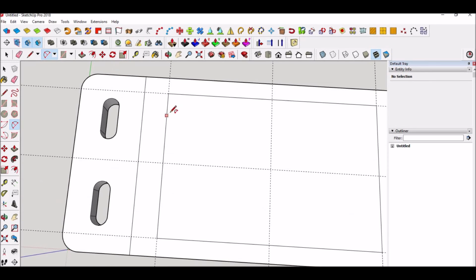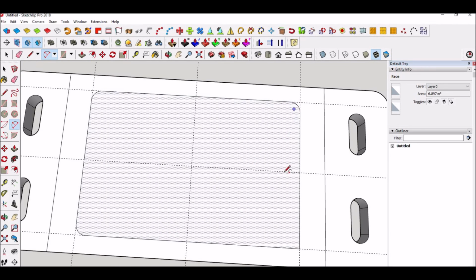So the same thing, click here, tangent, double click, and it did not do it for some reason. There we go. Probably clicked too fast. So 0.15, hit enter, it'll readjust it, hit A for arc, double click the corner, right there, right there. And then we can come up to here, double click.